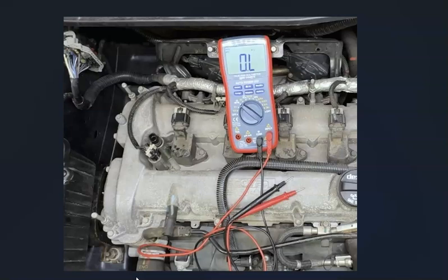You can also do a basic test on those solenoids with the multimeter. They'll have a set resistance, or ohms, that they should be at, so you can look those up for your particular Kia, and then test them and be sure that they're good. Because if there's any issue in the wiring or with those variable valve timing solenoids, then that's going to cause problems.